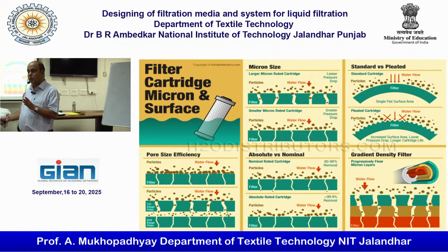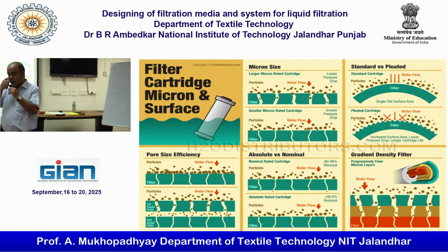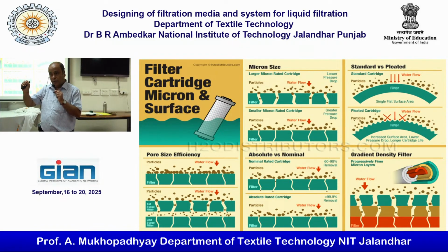Sometimes blinding happens, then others will also get affected. Blockage will occur if it appears in the bottommost layer. This will operate in the depth filtration case only. In surface filtration, we cannot go for a gradient density filter. Whenever we are making a cartridge, the basic idea here is that it is energetically more favorable, because you are separating the large matter first, then finer and finer material.